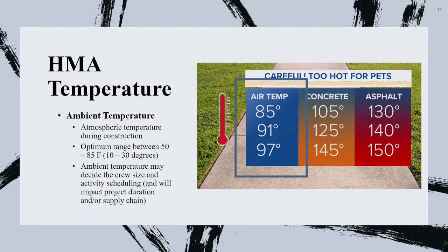They need to fix it even in the middle of the winter, in the middle of the night, and think also of traffic. It's huge. So blocking a road will cost thousands and hundreds of thousands of dollars. So they end up doing the work at night in the winter. So that's why they shift to warm mix. They go to temperature down to almost 100 degrees. That's about 50 or 60 degrees less.